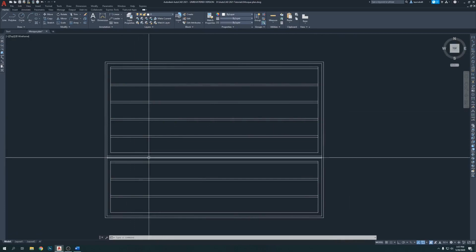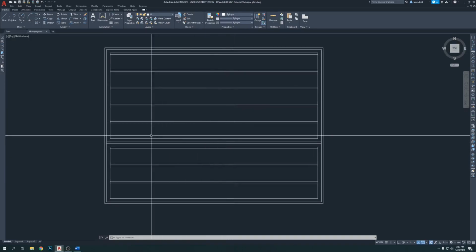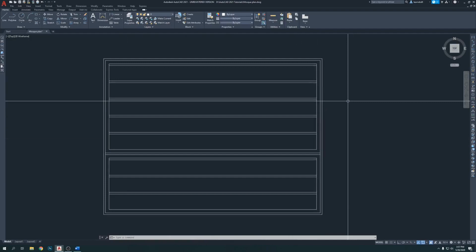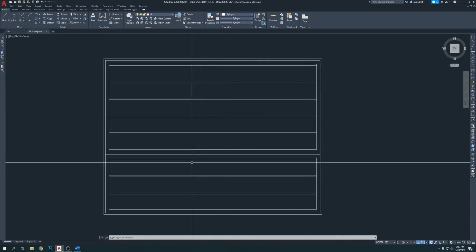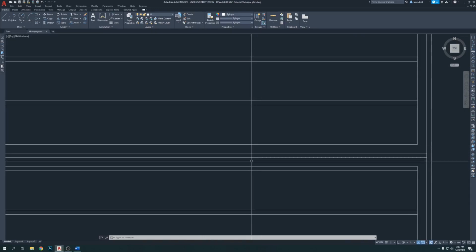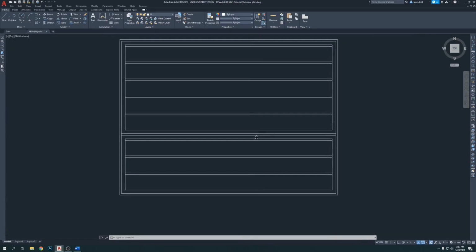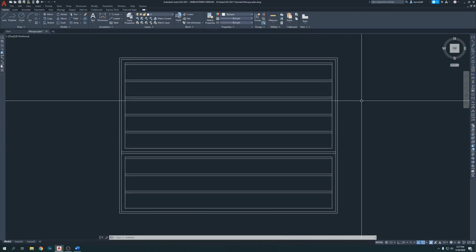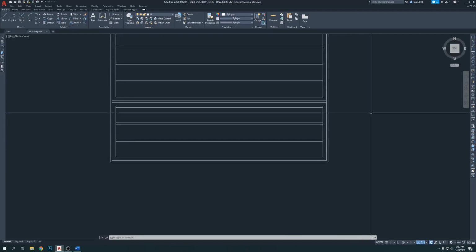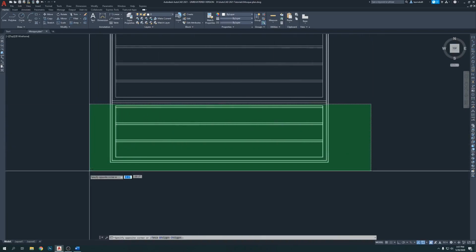Another thing, this wall we cannot make 6 inch, we need to make it bigger. Why bigger? Because a lot of load is going to be there, and the column is going to be bigger, and if we keep it 6 inches, then the column is going to come out this way or that way. So we need to extend this way, instead of into the main mosque.